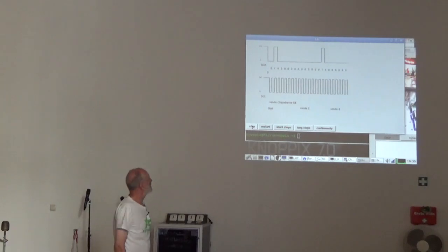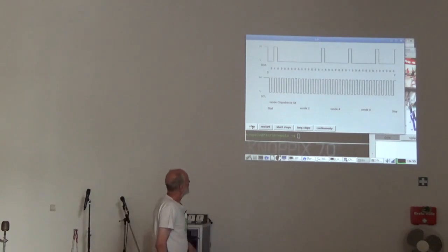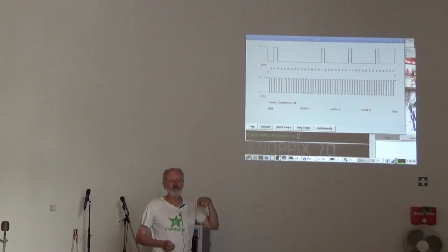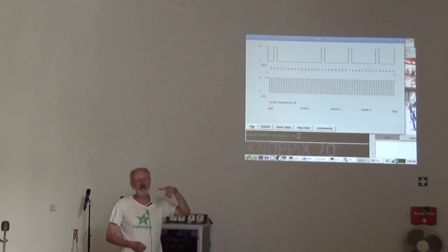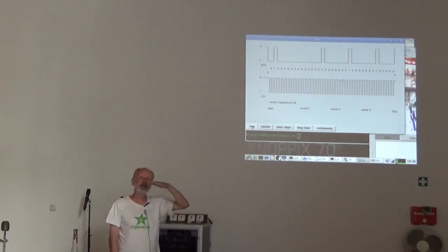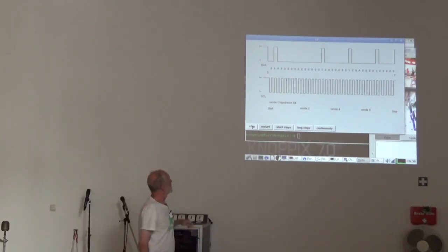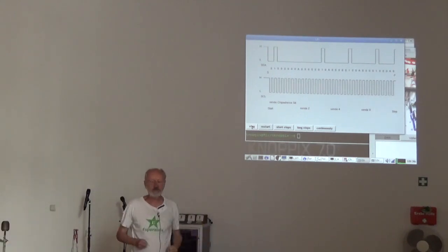It's not very fast, this demonstration. I first sent this chip address 64, so this is 0, 1, 0, 0, 0, 0, 0, 0, and then when I send 8 bits, the chip that is addressed must resend an acknowledge bit. So on the serial data line I send a high level, but the chip pulls the data line down, and so it acknowledges that it has been found on the bus.